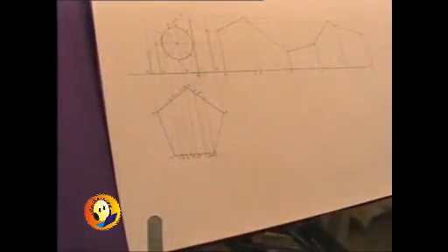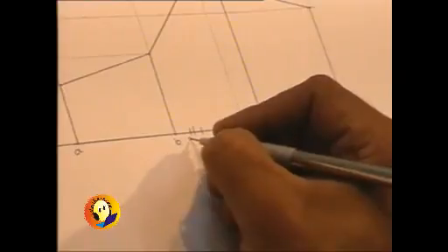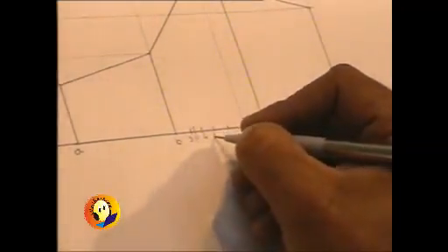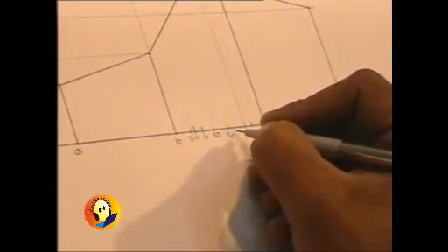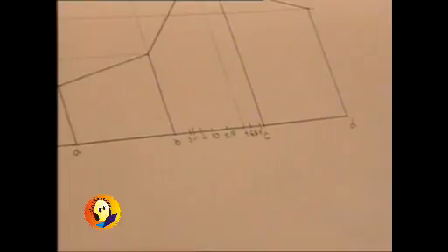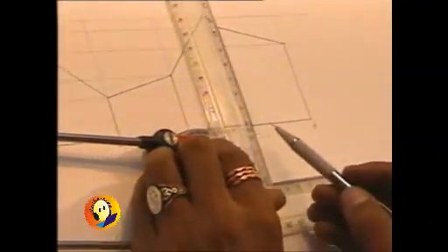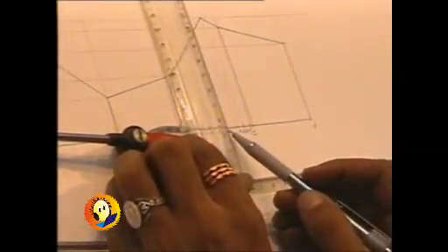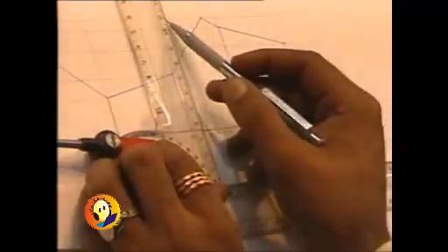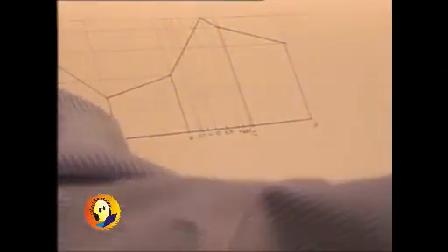So on the development now, we are required to name all these points. The sequence will remain the same. It is 3, then 11, then 4, then 10, then you have 5 as well as 9, then you have 6, 8 and 7, and also we are required to draw their generators on the development. In case of prism, the generators are all parallel to each other, so all these generators should be drawn for each of these points. So this is so far as face BC is concerned.